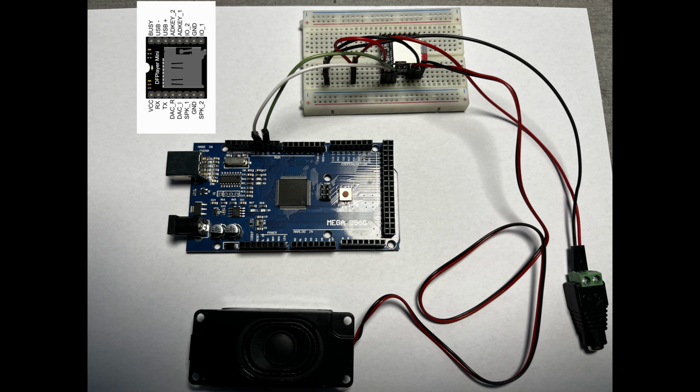If you look at the DFPlayer rotated 90 degrees, you will see a lower row of pins and an upper row of pins, and there's a little notch on the DFPlayer that needs to point to the left side. From a wiring aspect, we will just use the lower row of pins. Let's start by connecting the very first one, on the left lower side of the DFPlayer, and connect this VCC pin with our 5-volt power source.